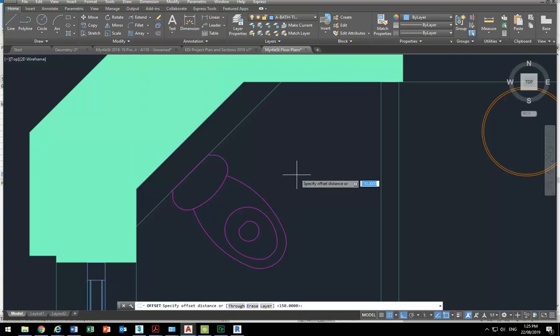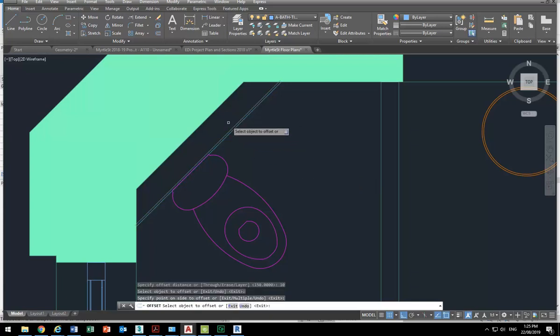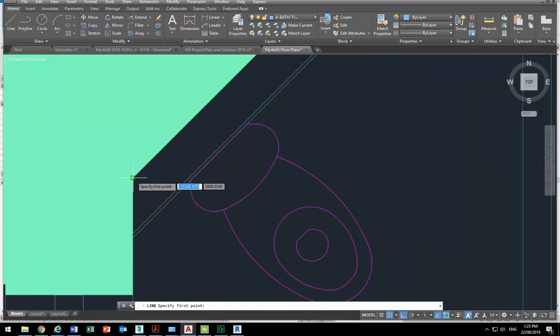What's the size of plasterboard? It's actually 13 mil, but if you're not sure, just round it off to 10 mil, and that's a good way to start. So 10 mil. That's going to be the thickness of the wall lining, and then you'll have some frame.